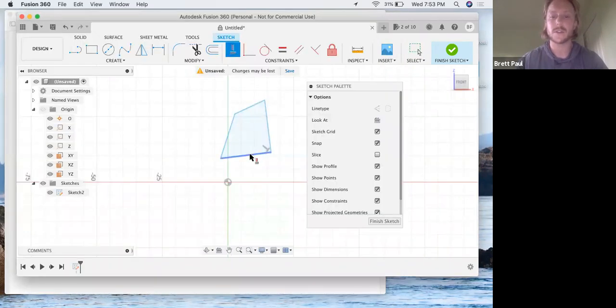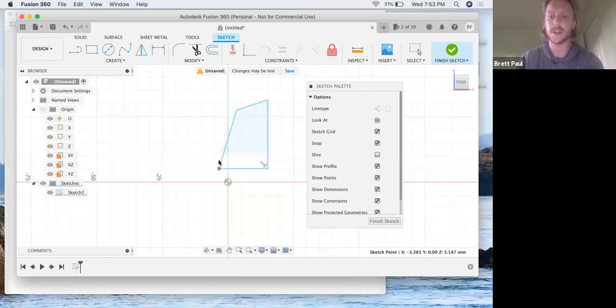Let's make a horizontal constraint here. You can see it right there. I'm going to exit that so that I'm not on constraint anymore. I can actually click on that constraint and delete it. I just hit the delete button on my keyboard. And you can see now, there are some other constraints here that aren't allowing me to change the angle of this, but it's more free form.